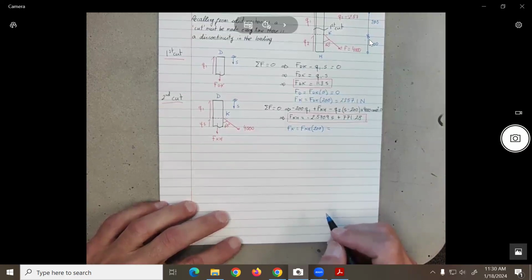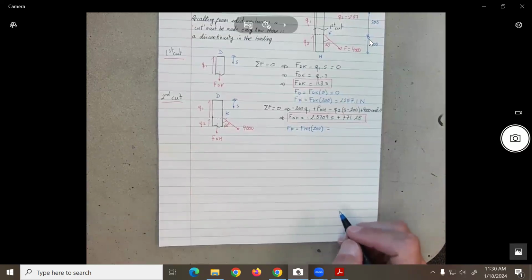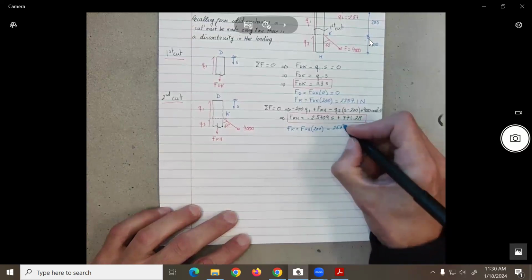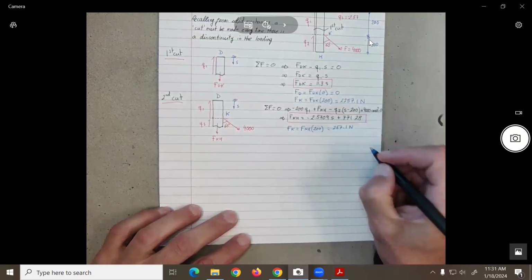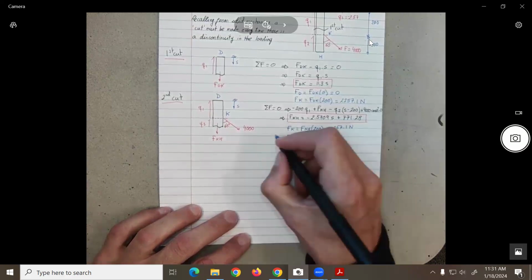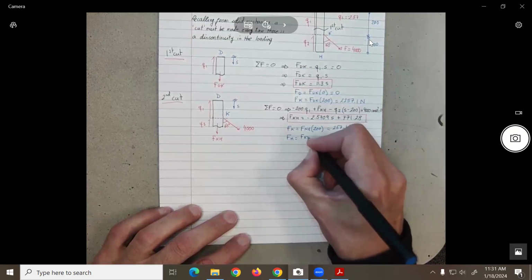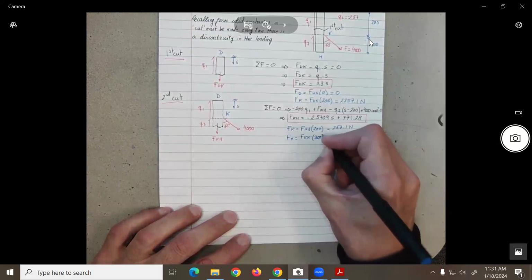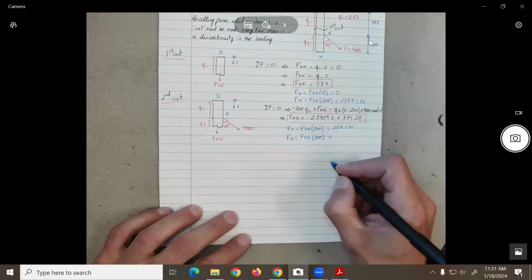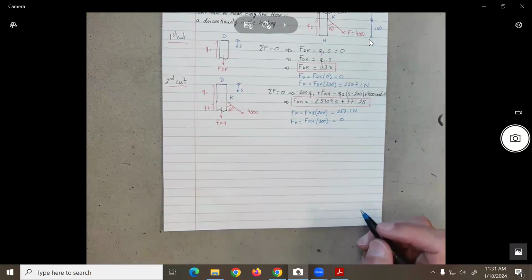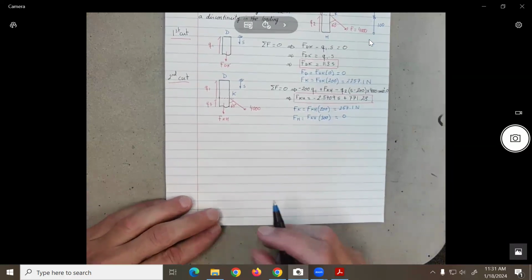And if we didn't do anything wrong, or you do the calculation, you're going to get over here that this load is 257.1 Newton. And similarly, the FH should be equal to FKH at 300. And if we did everything correct, that should be equal to 0, because as before, that will be the end of the lower flange, and that should be equal to 0.